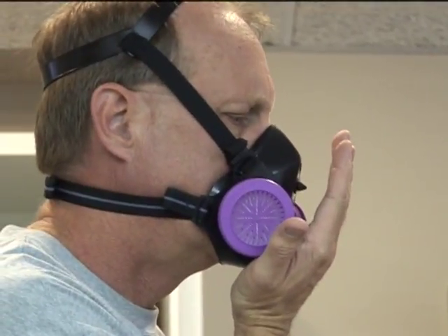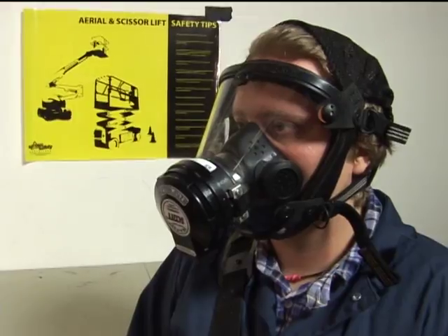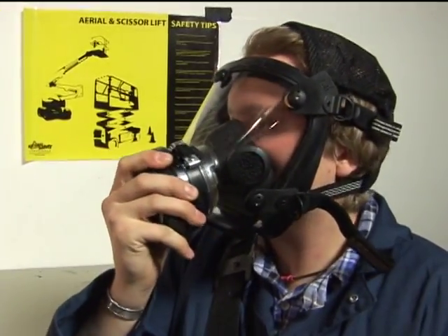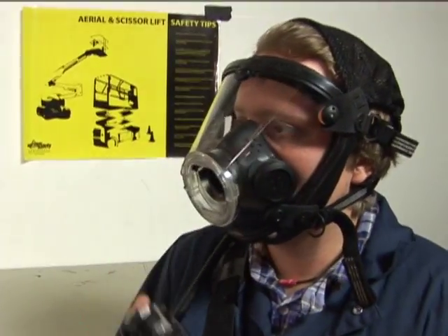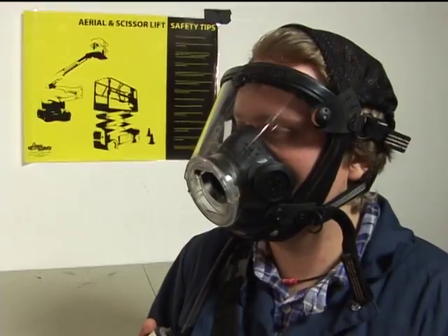A positive pressure check is performed by closing off the exhalation valve and exhaling gently into the facepiece. The face fit is considered satisfactory if a slight positive pressure can be built up inside the facepiece without any evidence of outward leakage of air at the seal. For most respirators, this method of leak testing requires the wearer to first remove the exhalation valve cover before closing off the exhalation valve and then carefully replacing it after the test.